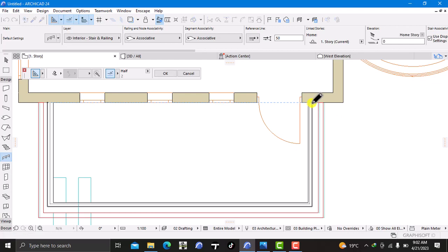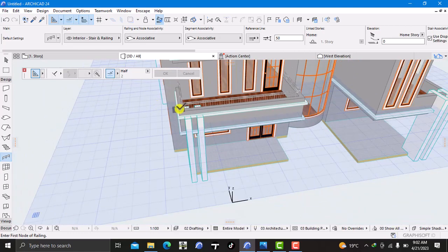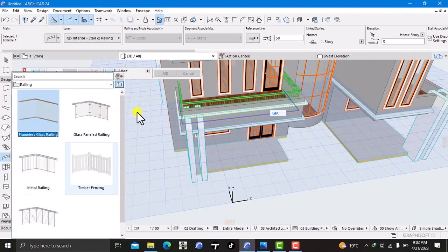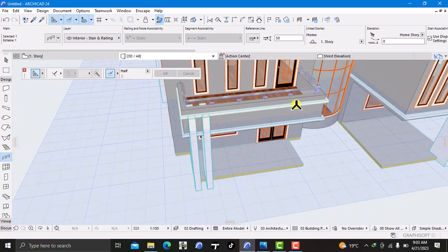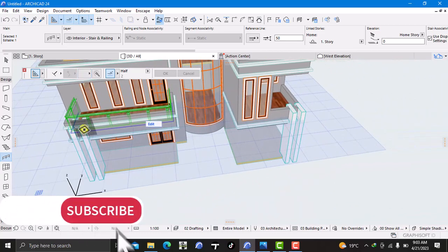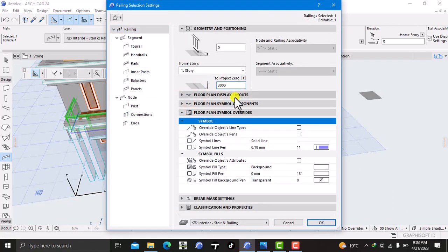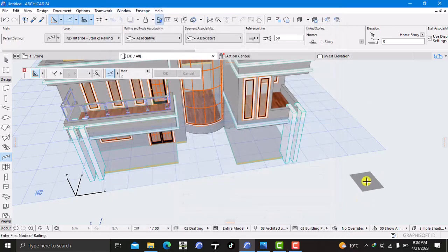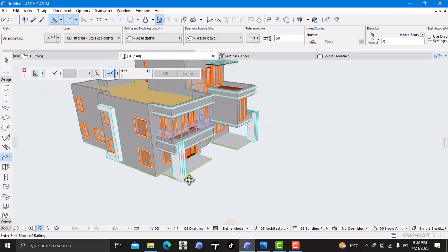You should take caution that you do it to be as seamless as possible. Okay, I'm still using the selection, hold the shift button, come to this rail, and use this glass panel type of rail. You see, so yeah, you can decide to use this. I just need to vary its height. Instead of 3200, let's work with 3600. See the level at which it's going to appear. So orbit this. So I have this